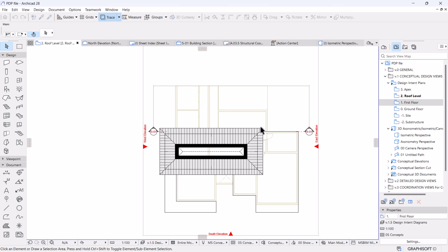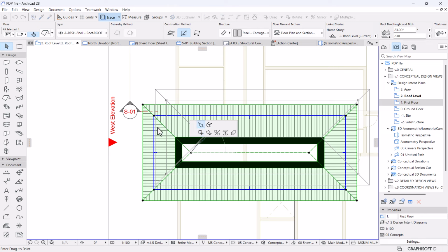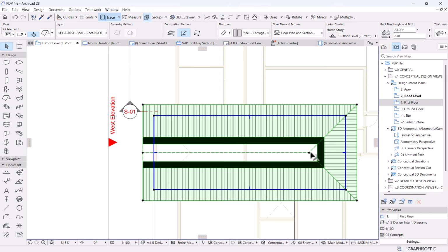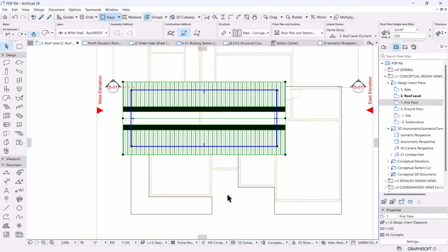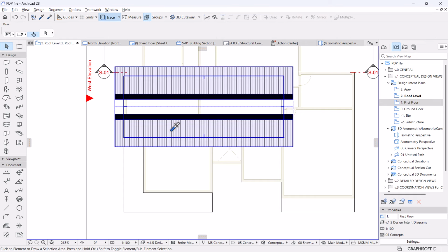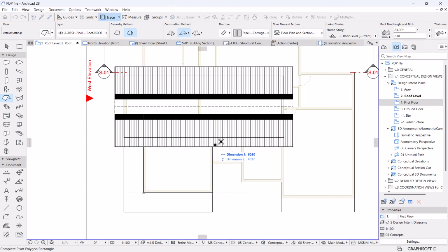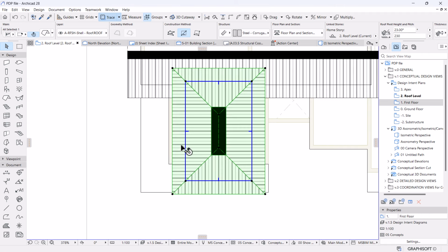Okay, I'm gonna select this roof and pick this ridge points, then I'm gonna get rid of the ridge point to there. Do the same and stretch it all the way to the reference point to have something like that. And then one thing that I need to do also, to place another one on this side. Yes, I'm going to rotate because the orientation is not what I want. And let's adjust before we kill the ridge.